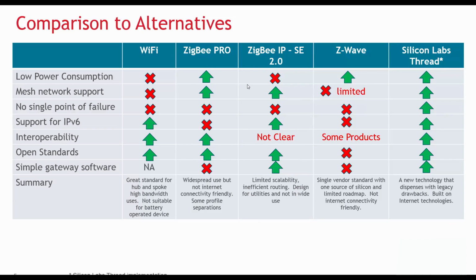And this would be used in conjunction with the ZigBee Smart Energy 2.0 application layer, SE 2.0, which was also designed to be IP-friendly for communication with the utility backhaul networks. While still an 802.15.4 based mesh network at the low levels, much like ZigBee Pro, the higher layers more closely resemble the full TCP/IP stack model used with Wi-Fi, and in fact ZigBee IP was designed to also support 802.11 as an alternative MAC and PHY.